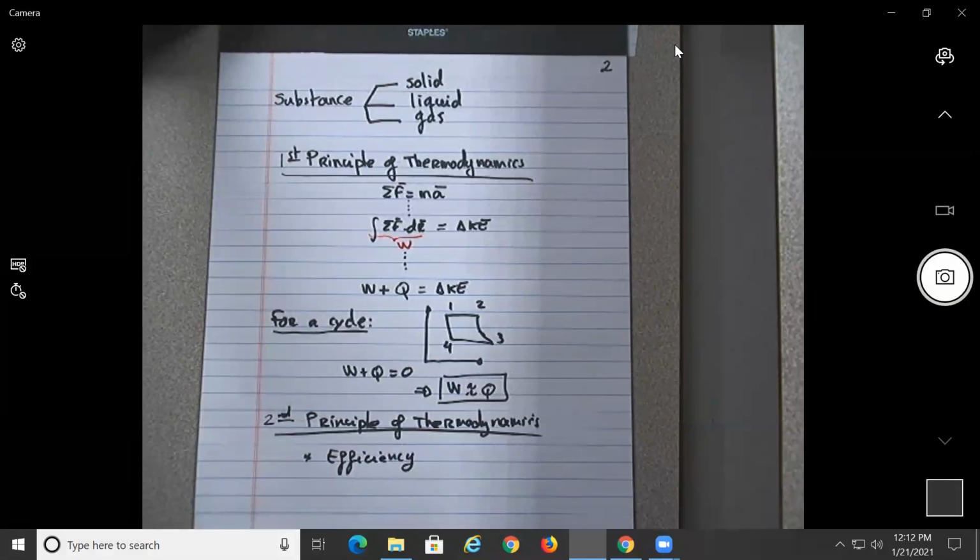So is the efficiency of your car, of the engine, the same when it's a hot day or a cold day? It's not the same. When is it more efficient? When it's cold or hot? Cold. And what is the reason? Because the more distance between the temperature of your engine and the surrounding temperature, the more work you can generate, no?